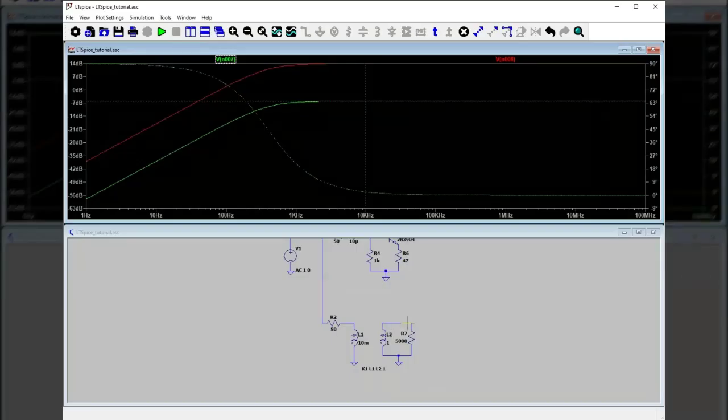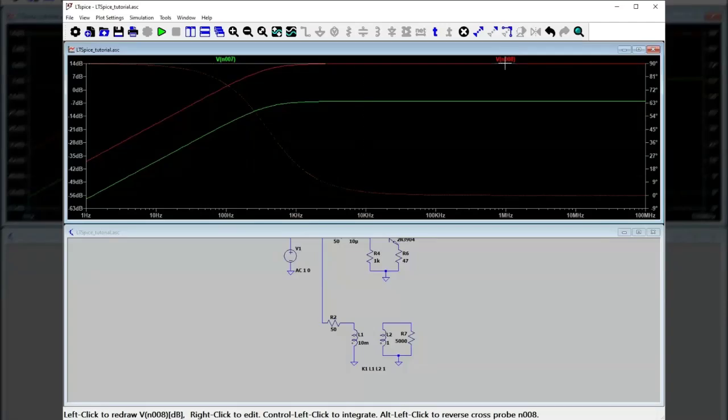Now, what voltage do we have on the secondary at that same frequency of 10 kilohertz? 14 dBV. So we got minus 6 dBV here, 14 dBV here. There's a 20 dB difference, and that is 10 to 1. 10 to 1 voltage multiplication. Another way of looking at it, half a volt here, 14 dBV is 5 volts. How do you know that? 20 dBV is 10 volts, and 6 dB less than that, 5 volts.